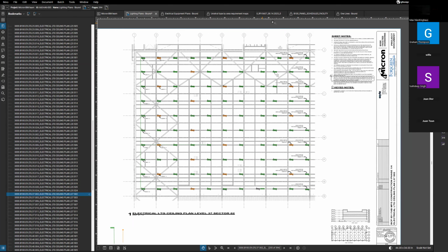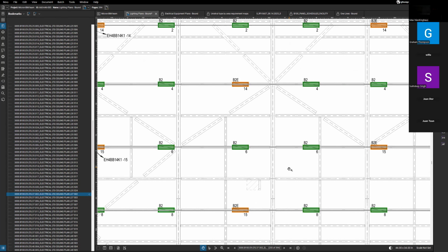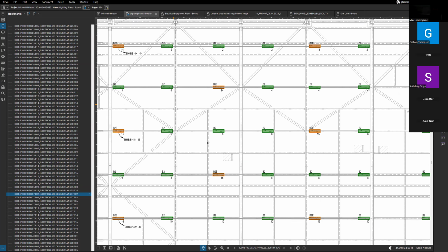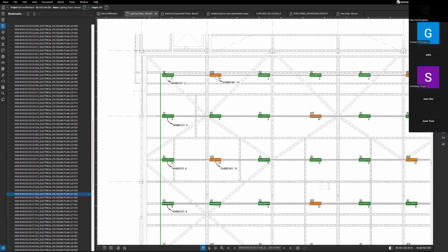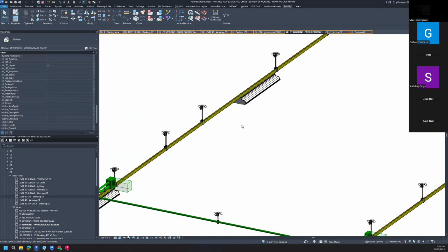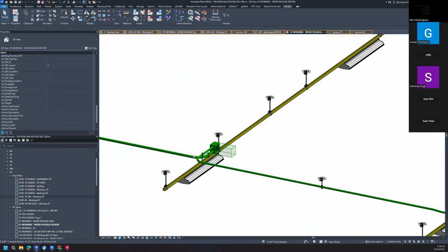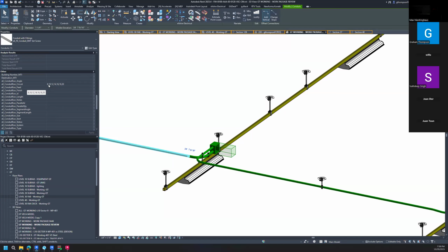But here's all the lighting for it. Okay, and so I'm looking at an RCP. I'm drawing in lights. I'm marking up where I'm putting my lights and where the runs are and how I'm supporting it. I'm also looking at the circuitry and running all this out. So I'm actually modeling all of this, all the lights, all the circuits, how they clamp, where they clamp to the beams, what conduits are there, what's feeding. If you click on this, you can see there's going to be circuit. This is fed in an inch and a quarter off of, it's feeding the L37 lights.